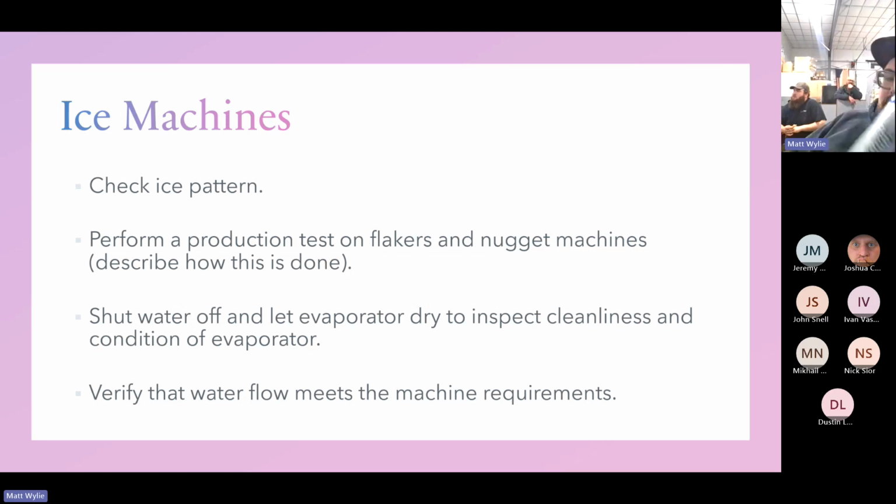I uploaded a picture of a water filter. Some restaurants or ice machines have them. Check the pressure, and then refer to the installation instructions on the ice machine. The specs will say how much water, what minimum water, and what temperature of the water. Like Hoshizaki, the inlet line has to be 1/2 inch, can't be any less. Manitowoc, you can do the 3/8